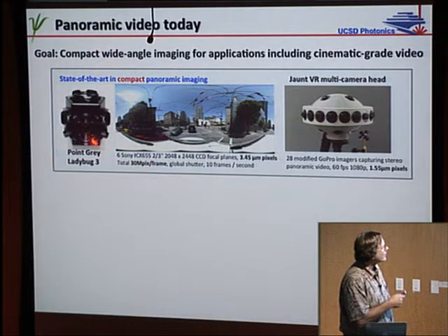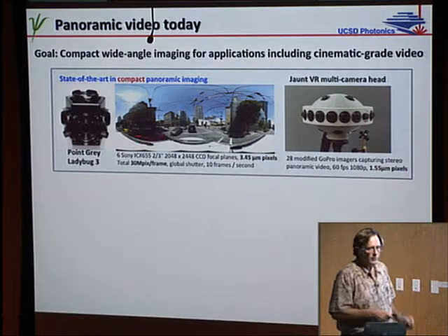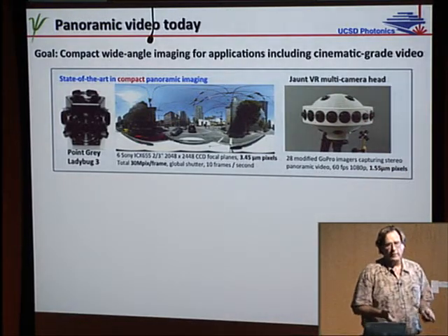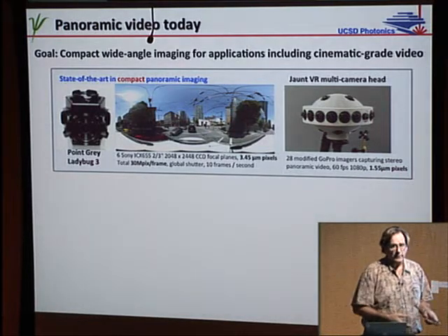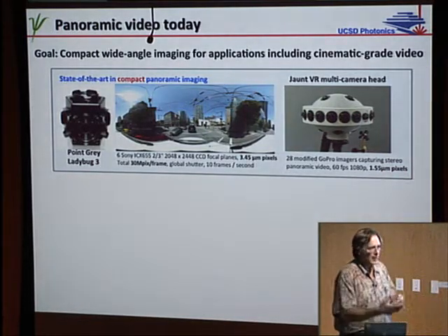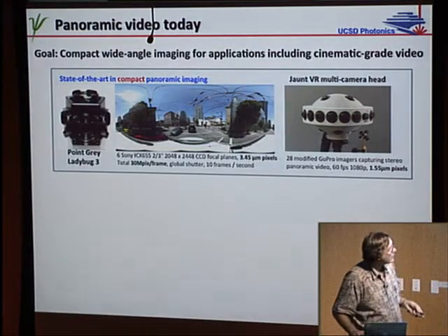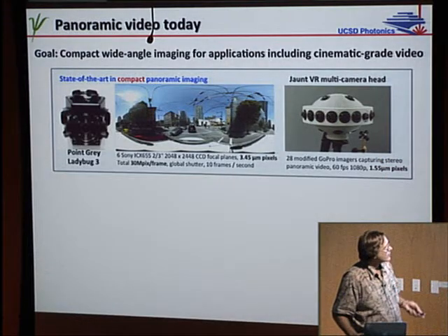These are small cameras with small pixels. A GoPro, although an excellent camera, a really outstanding camera, is a 1.55 micron pixel. It has a limited dynamic range and a limited electron well depth. It is intrinsically not a great sensor. It's relatively easy to make that lens, but the sensor limits your performance.